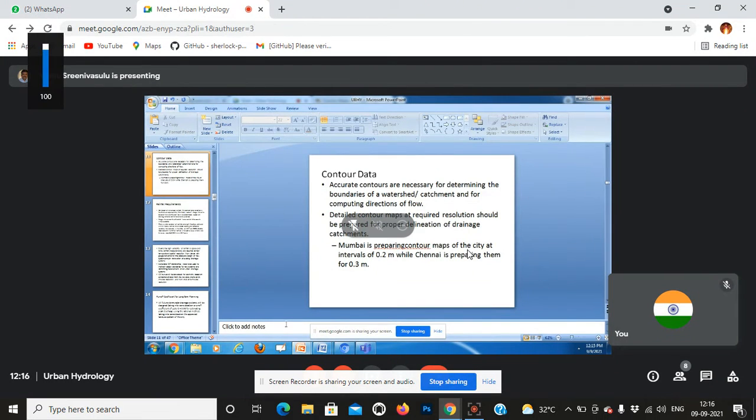You have to calculate the runoff. To calculate the runoff, there are several methods. Empirical formulas are there, and then the SCS method is there, or the rational formula is there. Okay. Once you calculate the runoff coming from the catchment, right, and to discharge that runoff,